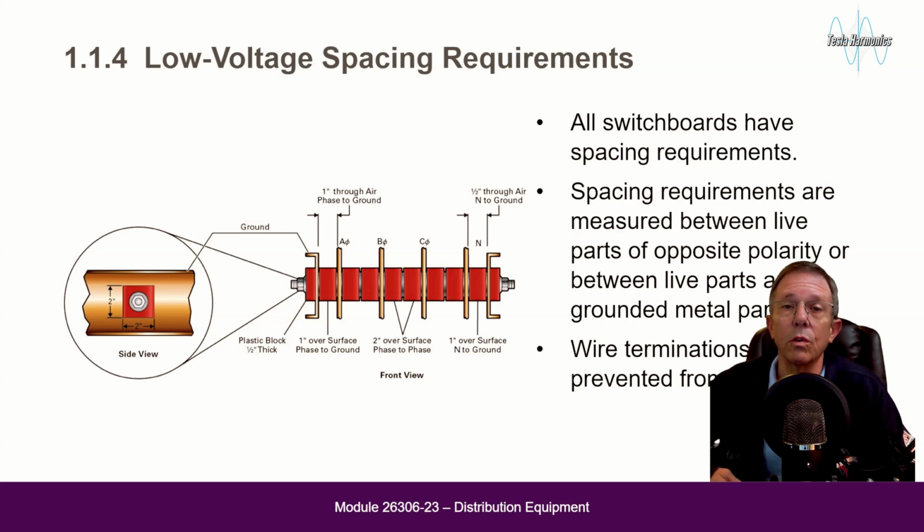Low voltage spacing requirements. All switchboards have spacing requirements. Spacing requirements are measured between live parts of opposite polarity or between live parts and grounded metal parts. Wire terminations must be prevented from rotating.